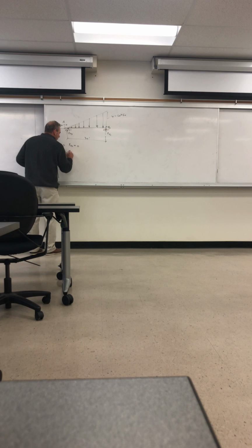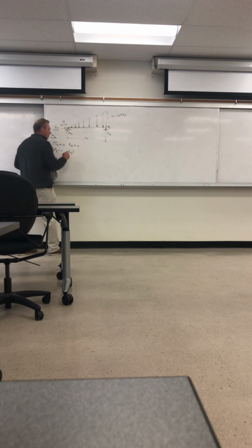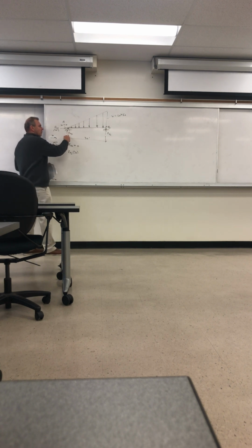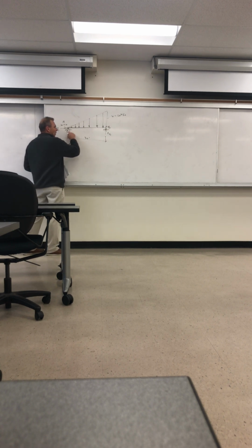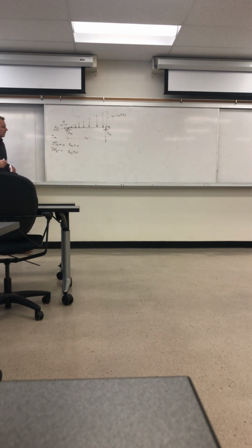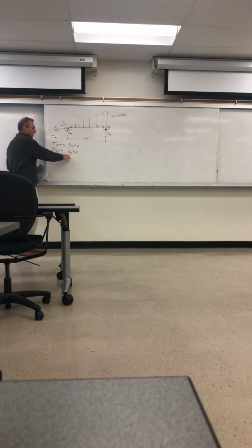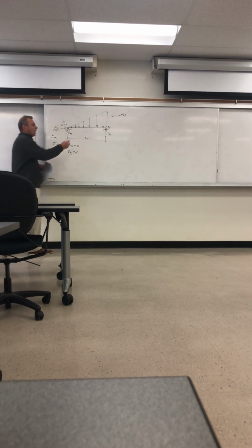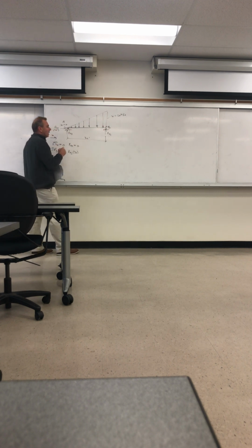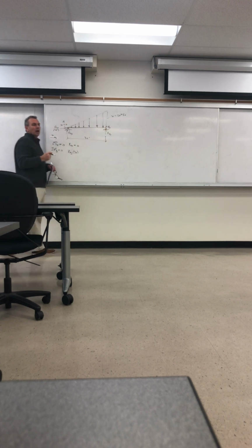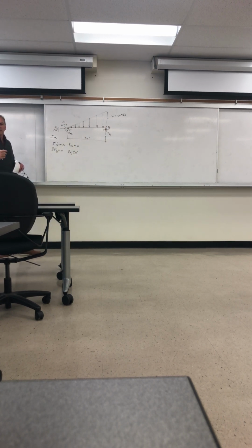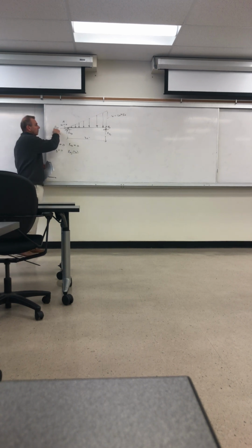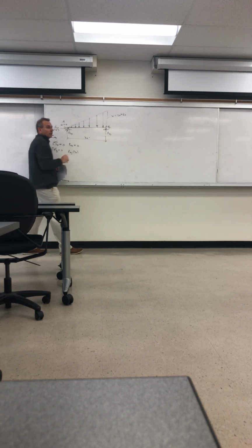And that gives me R sub Ay multiplied by 30. The applied loading doesn't have anything to do with the moment associated with this, right? This is reaction Ay times length, in terms of the equation at least. It has a lot to do with the actual final value of R sub Ay. So that's the clockwise moment about an axis coming out of B from this reaction. This horizontal reaction, even if we had a value, is going right through B, so its contribution to the moment equation about B is 0, because it's that force times a 0 normal distance.